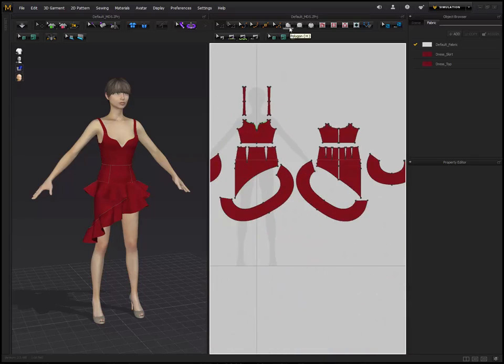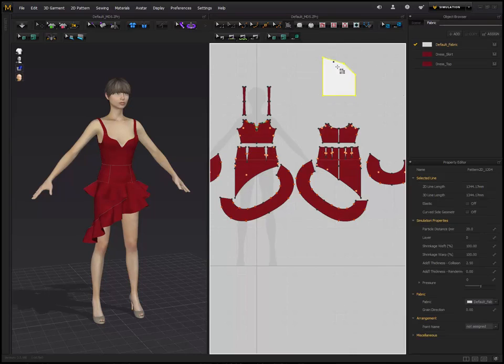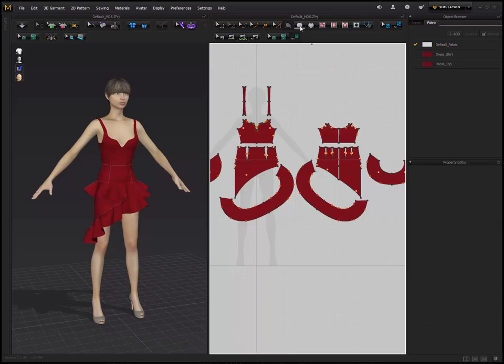Next 3 options are the basic polygon options to create the fabric. The middle one creates a rectangle, the far right one creates a circle, and the far left one you create by clicking. As you hold shift, you can make straight lines, straight 45-degree angles, but you could add as many points as you want. Click at the end to finish it. Personally, I always start off with a rectangle or a circle.